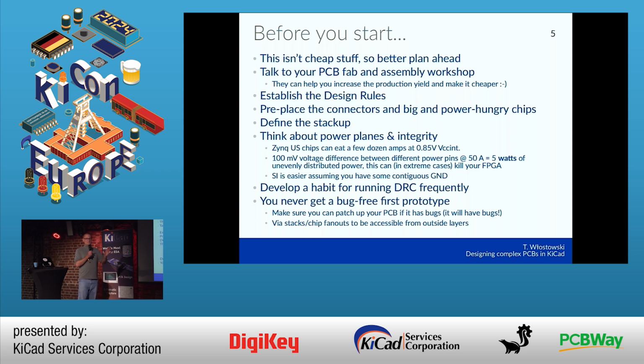And some of these chips are pretty big, like 6 by 6 centimeters, 2000 plus pin BGA. So now imagine if you have a bit of a voltage drop over your internal power plane. Let it be a modest 100 millivolts. 100 millivolts times 50 amps means 5 watts of power distributed across the bonding to your chip. This can simply evaporate it soon after the board is connected.